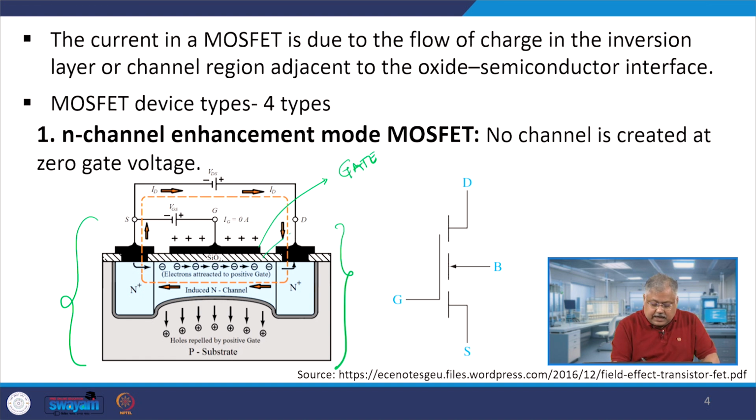This hashed line is the oxide layer, and this whole thing, this blue and all these things, is basically my semiconductor. So that's the reason it's known as a MOS device. But now we have added 2 extra regions here. One is known as the source region, and that's the reason it's shown as source here, and I have a drain region which is N plus region.